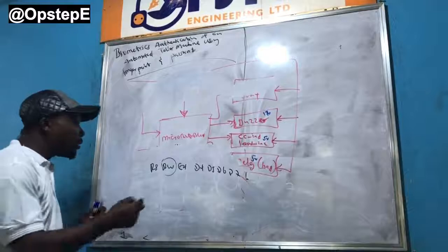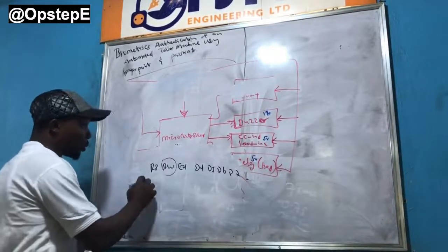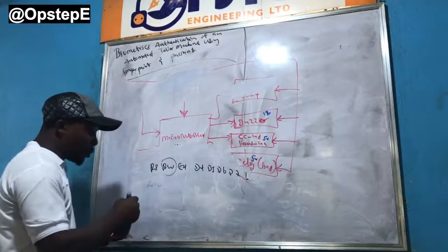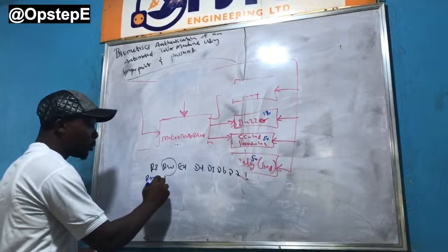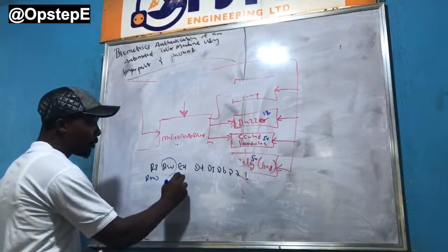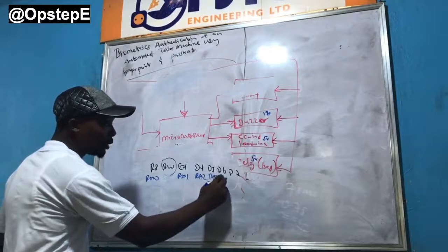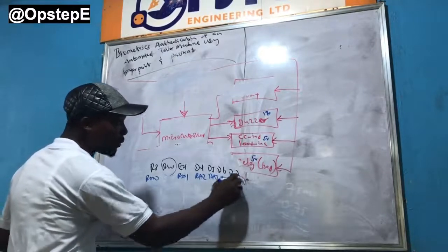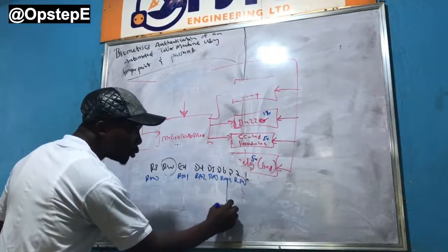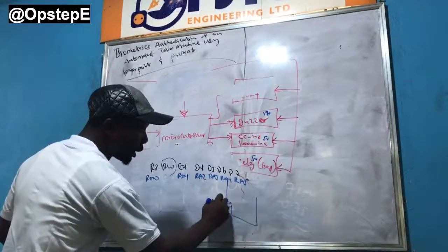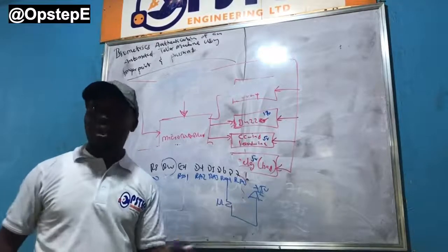What that means is that my RS will now be with my RA0, RA1, RA2, RA3, RA4, and RA5. So this RA4 should go through a 10K resistor to VDD. Does it make sense? Otherwise, the LCD will not work.